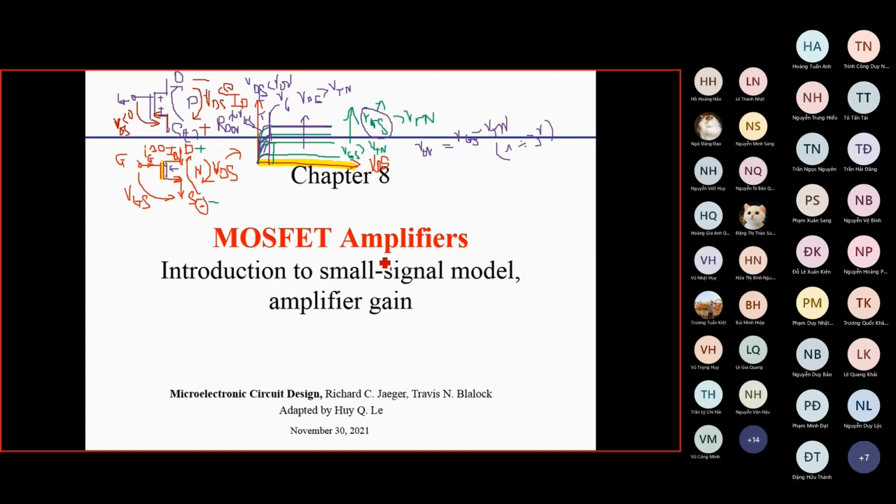Okay, so that is the very basic thing. As with the BJT, when the transistor is in the cut-off mode, you can replace the transistor by an open circuit. Between the drain and the source, there is no connection, so the current ID is equal to 0. The transistor can be used as an open switch, a turned-off switch, right?